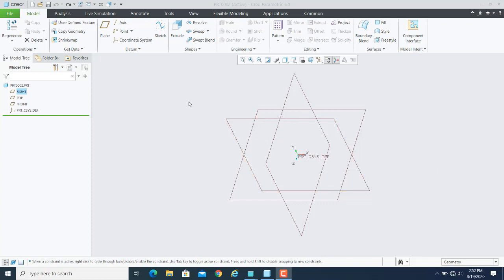In today's video, we will discuss the rotational blending and general type of blend in detail. But before that, let me show you the parallel blend option in Creo environment also. So right now I am in the Creo environment and I am in the part module. In the Protrusion menu, if you click on the shapes, you will find that parallel blend option.